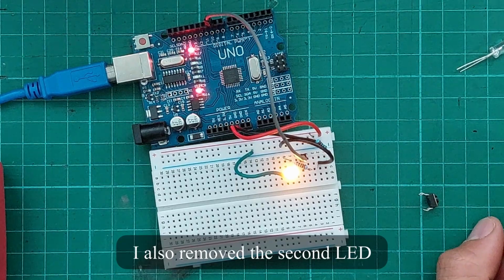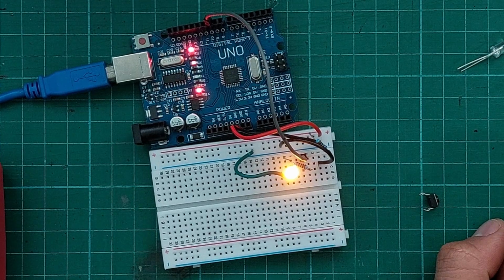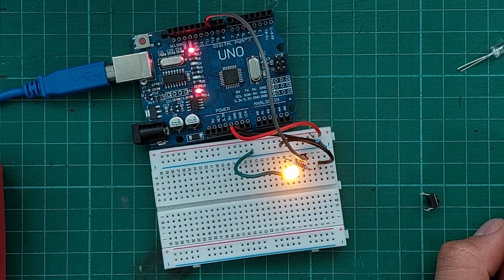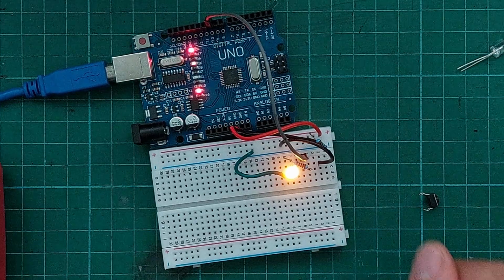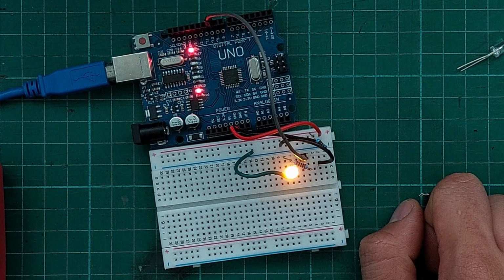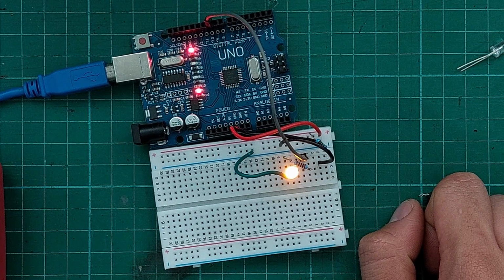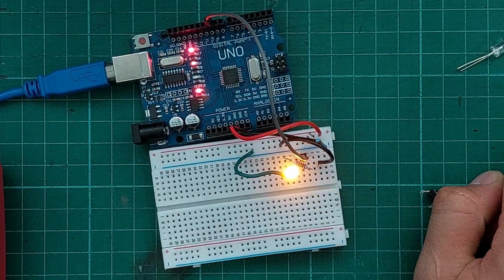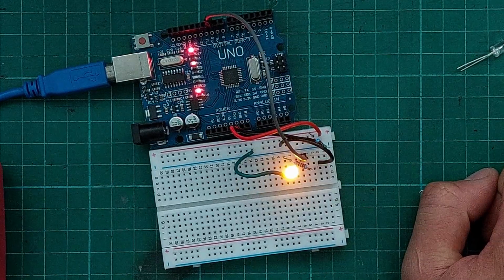Okay, I flashed the code, and as you can see, the LED is growing brighter, but really, really slowly. So I'm going to change the delay to 10 and upload the code. We should see that the LED goes up and down much faster because it's going to delay less. Let's just let my compiler do its thing. It's a bit slow, and we should see that soon. Okay, it's uploaded, and we see that this thing goes up, goes down, goes up, goes down. It has this fade effect. So that's exactly what we wanted to achieve.